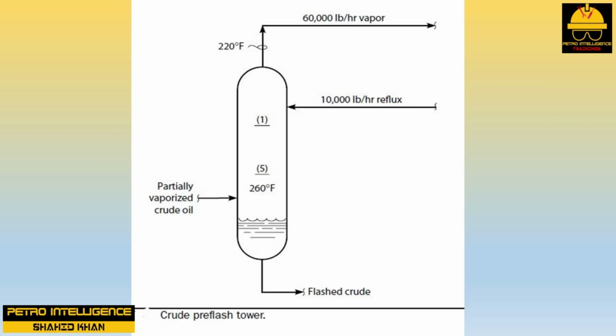Conversion of sensible heat to latent heat. When we raise the top reflux rate to our pre-flash tower, the tower top temperature goes down. This is a sign that we are washing out from the upflowing vapors more of the heavier or higher molecular weight components in the overhead product. Of course, that is why we raised the reflux rate. So, the reduction in tower top temperature is good.